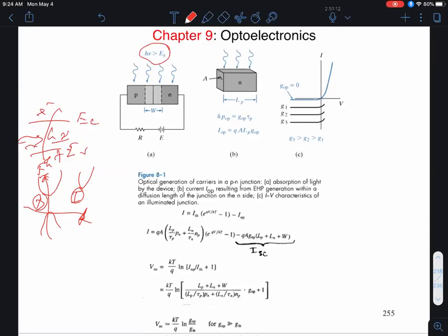All right. So what we had mentioned in the context of BJTs, we had basically used this picture to motivate how a BJT operates. Okay, so I'll review that. What we had said then was, if you look at a PN junction device and its IV characteristics, in forward bias we have current which goes up exponentially with voltage, e to the power QV over KT minus 1. But if the bias is negative, this first term becomes basically 0, and I get minus I naught. Okay, and that's your supply limited reverse leakage current, right?